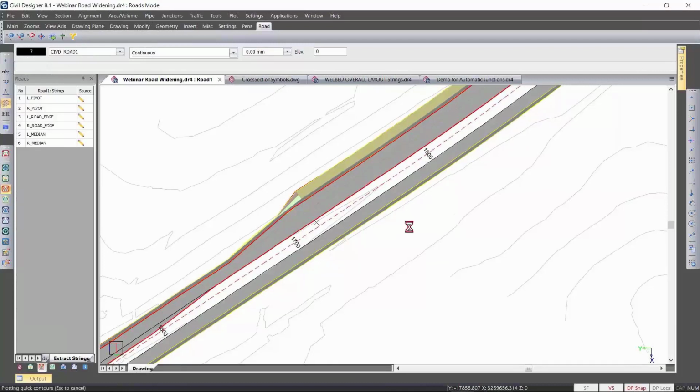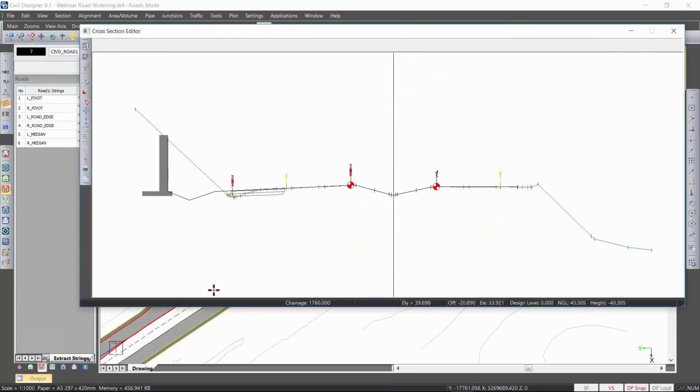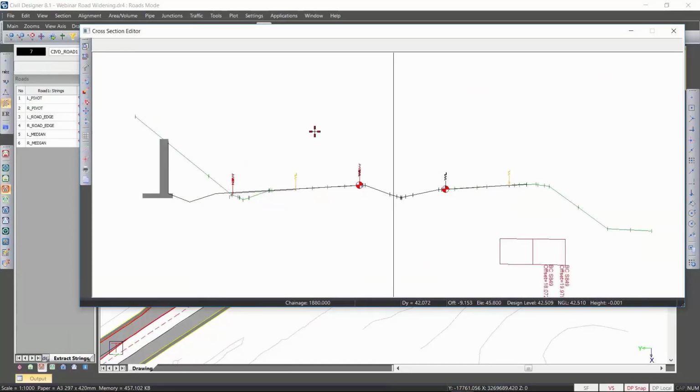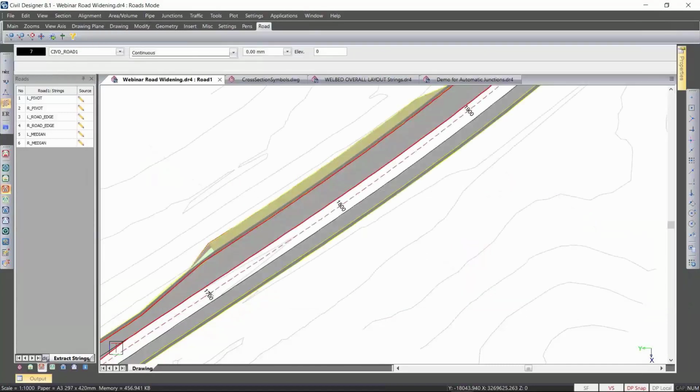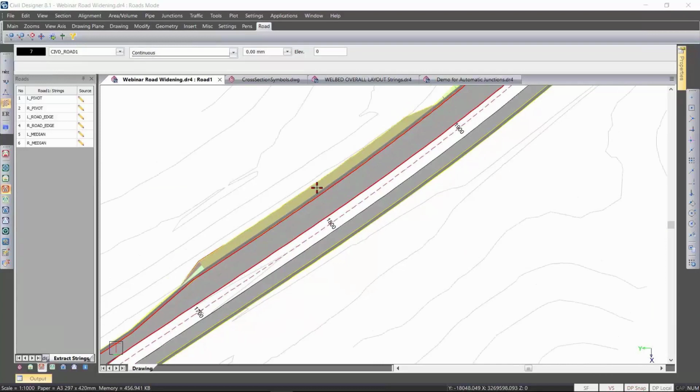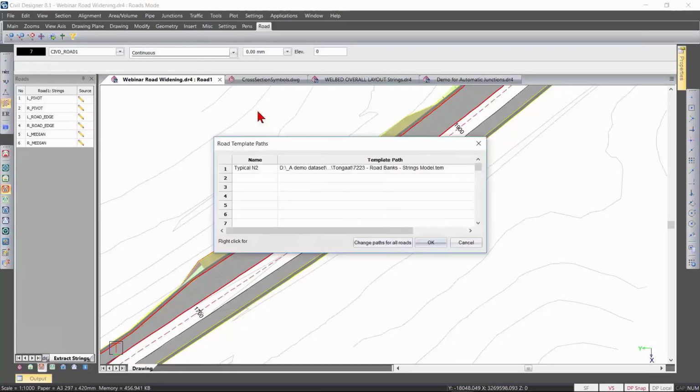In this case it's a variable height retaining wall that we've added into our standard components. If I go through that chainage range, you can see that the retaining wall is being sized as it goes along and just intersecting with the ground. Maybe I should touch on those new special vertical movements that we've incorporated for that variable height retaining wall.